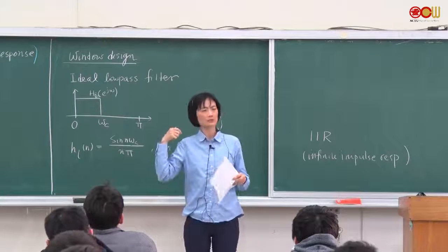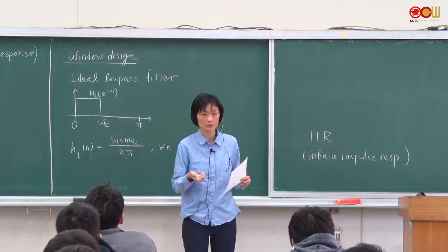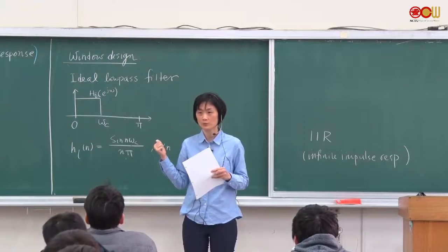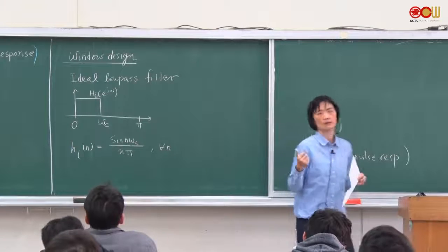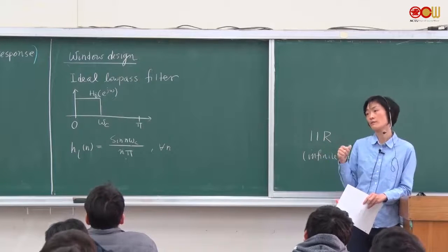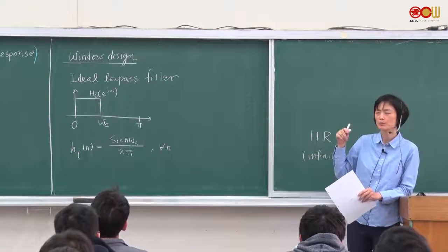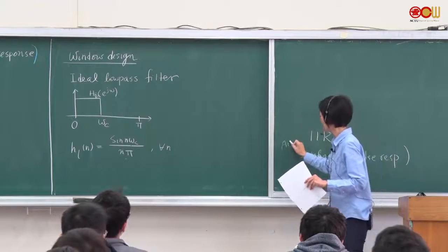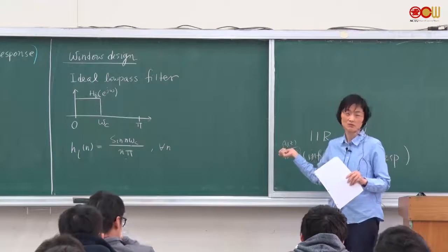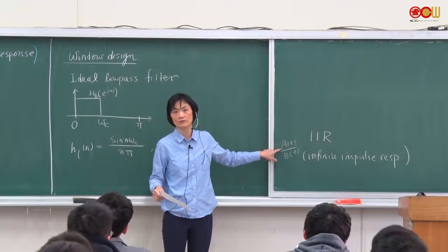But we know in an IIR filter, if we have those rational transfer functions, then we would get an IIR impulse response, right? Then, is this rational? Remember, all the systems that we implement are rational, right? So is this rational? Have we ever expressed the ideal low-pass filter in this form? No. It cannot be expressed in this form, right? Because this is not rational. Just look at the zeros. The numerator would have the zeros.